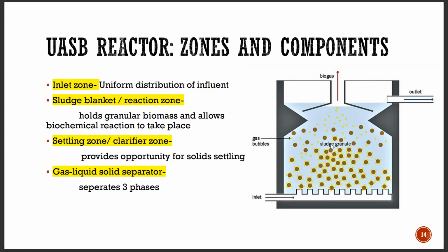So this biogas, as it rises up, will get collected into the gas collection dome, and the clear water is taken through this sloped surface, and it is taken out using this outlet, and the decomposed solid particles that are present in the water are allowed to settle, and this contains bacteria. So these anaerobic bacteria will actually be helping with the remaining digestion process.